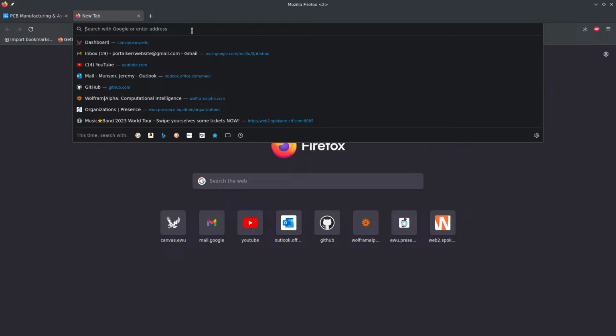And this is the motor driver. So I have Arduino, all the support stuff for the Arduino. I have these huge MOSFETs to drive the motor, and I drive the output pretty much the exact same way I just showed with the LEDs, using these. These are the ones I have a reel of. To drive those, it's like amplify, then amplify to get to the motor.